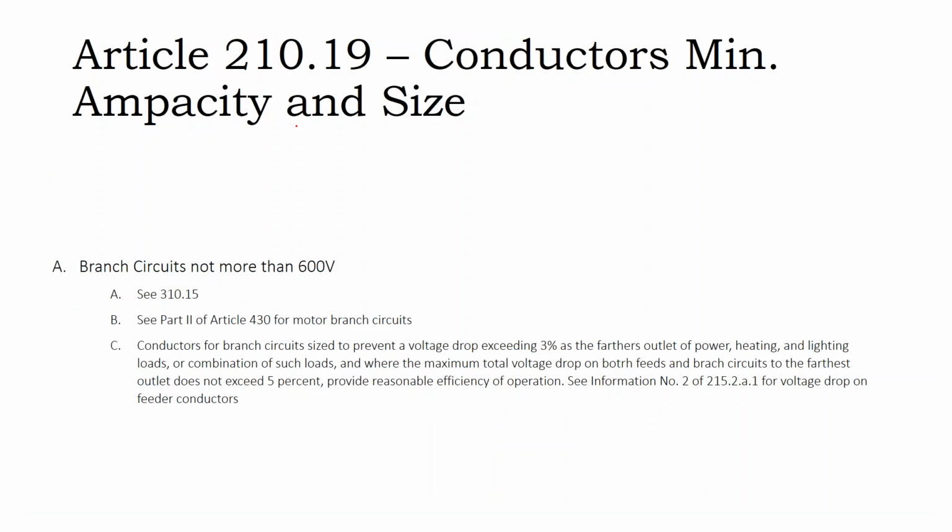So if you're installing a generator and you're putting in a ground rod right next to the generator and you're bonding the neutral to ground on that generator, then you need to make sure that your neutral-to-ground reference from the utility side is completely opening up when it comes time for your transfer switch. Otherwise, you just share it.